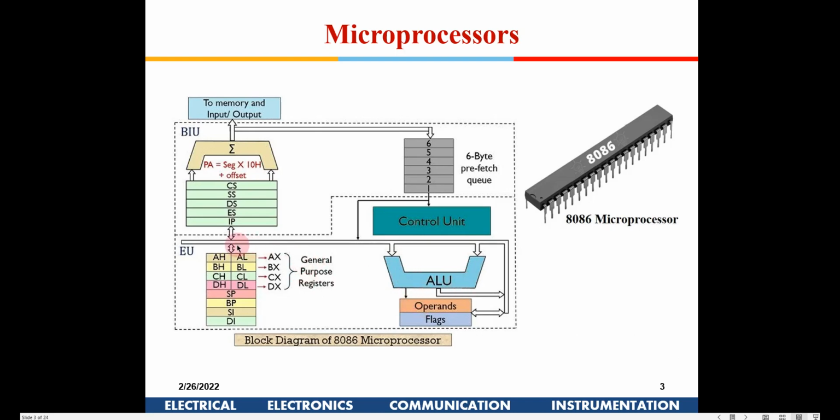Either you can have inputs from two registers itself, or one of the inputs coming from the register, and one of the inputs coming from the memory. Generally two inputs from the memory is not allowed. So in certain classes of microprocessors you can have both the two inputs only from a register. We'll see those classifications later on.